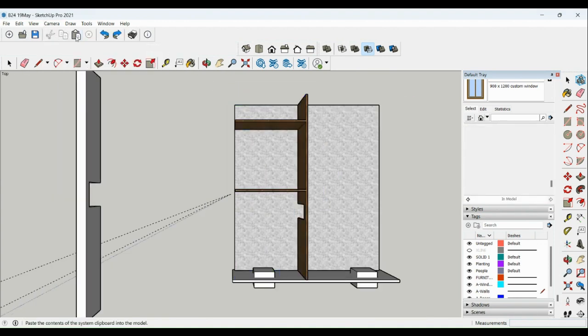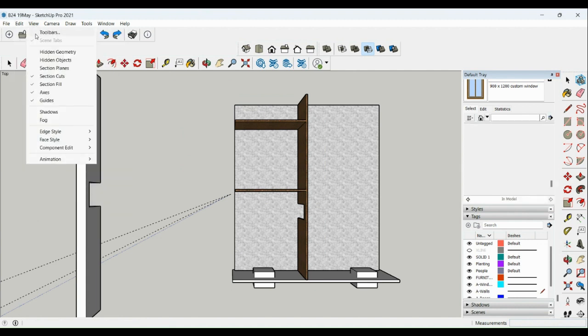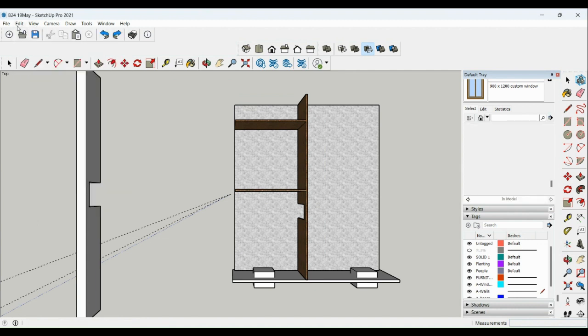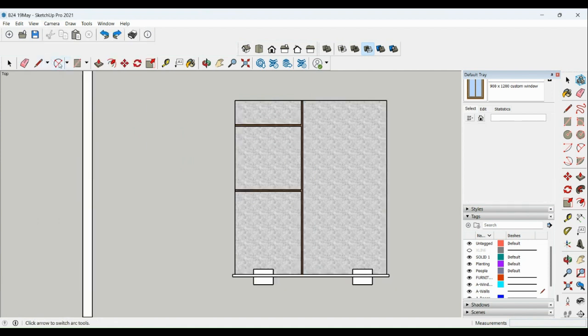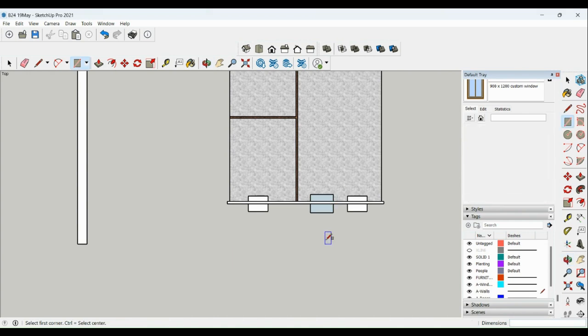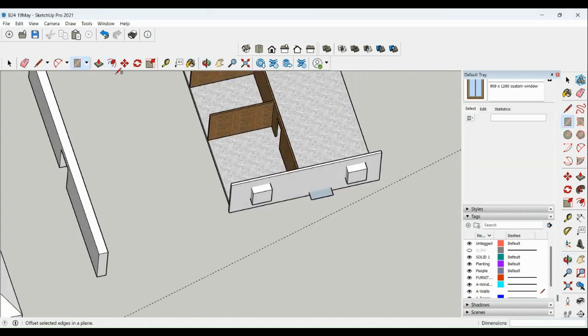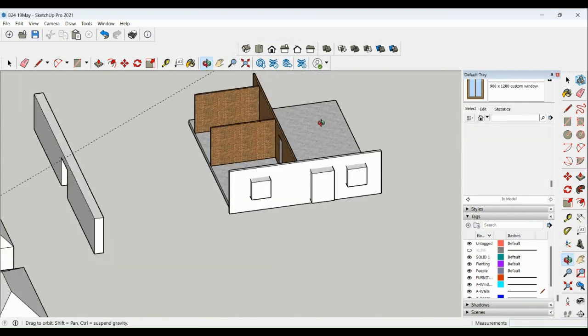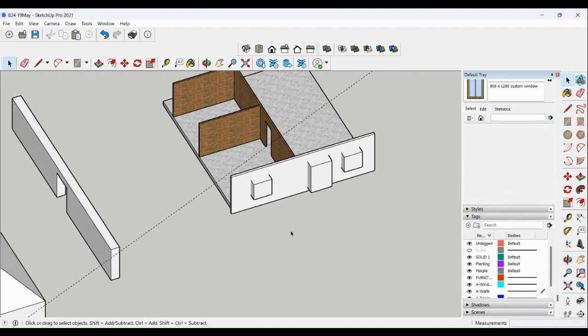Okay, let's make sure that this is seen as parallel projection, so it's flat, right? So now let's create a rectangle, maybe here. Okay, and then let's push it by how much? To 100. Enter. Okay, so now, what's next?